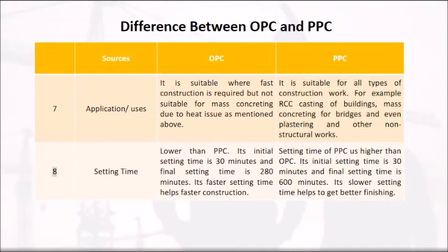Eight, setting time. OPC's setting time is lower than PPC's. Its initial setting time is 30 minutes and final setting time is 280 minutes. Its faster setting time helps faster construction. The setting time of PPC is higher than OPC. Its initial setting time is 30 minutes and final setting time is 600 minutes. Its slower setting time helps to get better finishing.